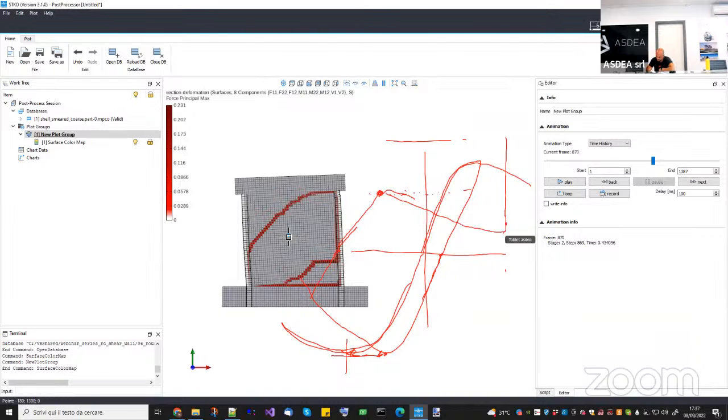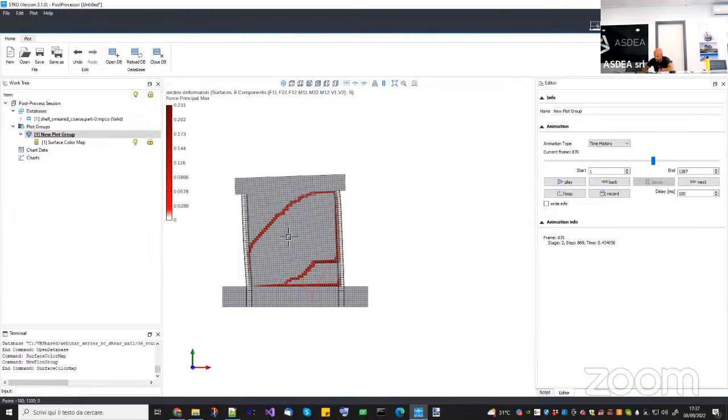Instead, with the beam truss model, what happens is that when I go here, I have a certain pinching effect and I start reloading here. And so here, I will hit my, let's say, yield surface or yield limit, and then I will start going back. So this one seems not important, but when you have a lot of cycles, it is very important, because at the end of the day, what will happen with a three-dimensional model, if you expect a backbone like this, if you do a monotonic test, is fine. If you do cyclic, you will see something like this.